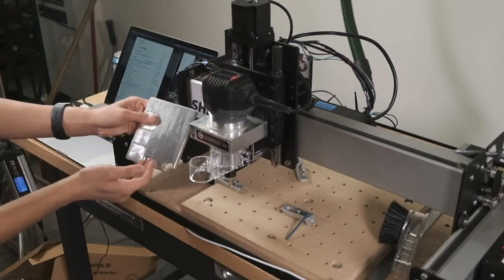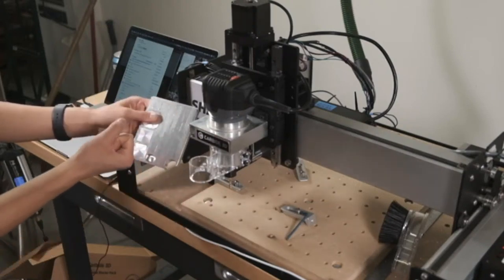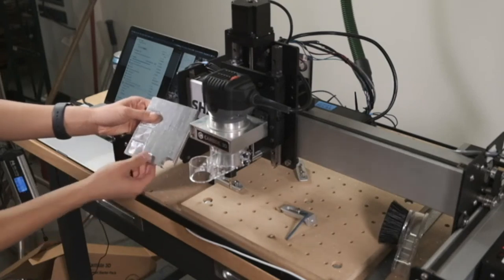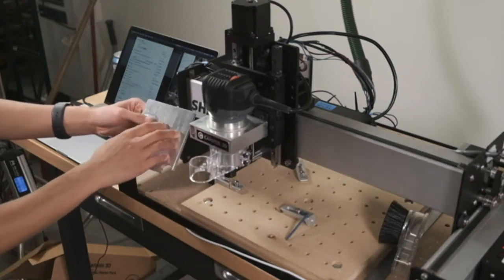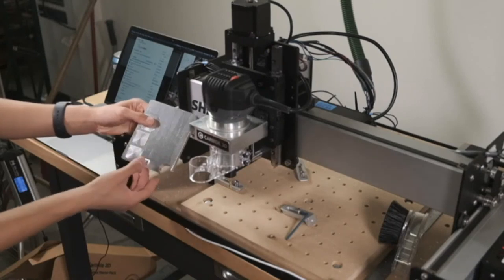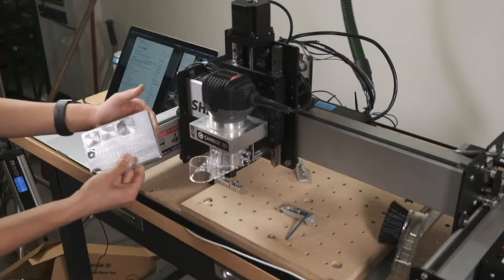It does build up heat. You are using a tool to literally rip aluminum atoms apart, and that's going to release energy. So it will get warm. If you're cutting something large, but the heat can dissipate out, that's fine. If it gets scorching hot, that's a problem, especially if you're using double-sided tape, because the adhesive gets weaker the hotter it gets.